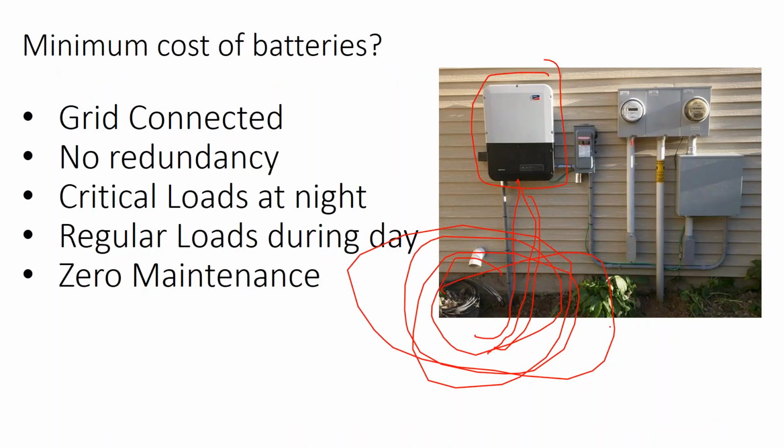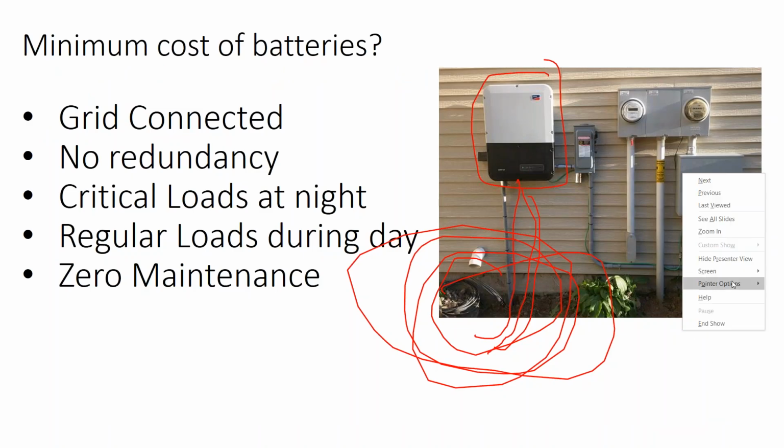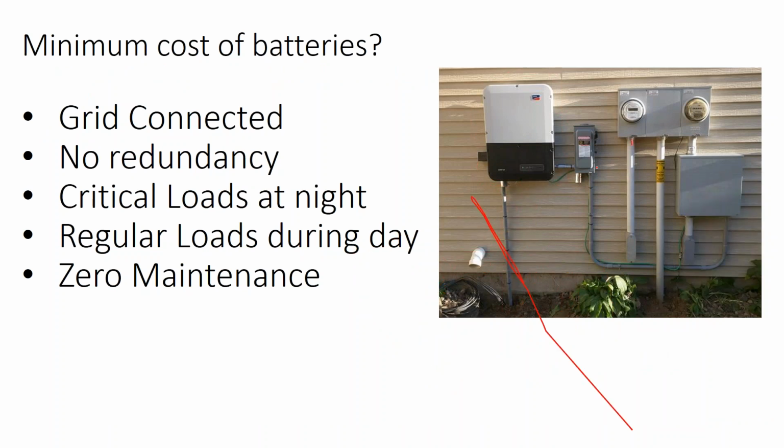So one thing that we thought about doing was getting rid of the knife switch disconnect. So here we have our knife switch disconnect. That's a utility required mandate, but it's not part of the National Electric Code. So what we told the utility originally is that we were doing a supply side connection. We've got underground lines coming up from the utility.